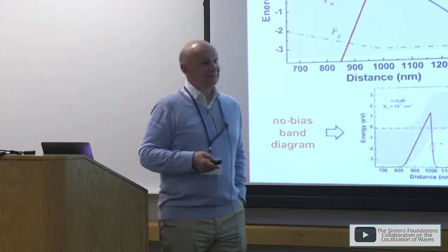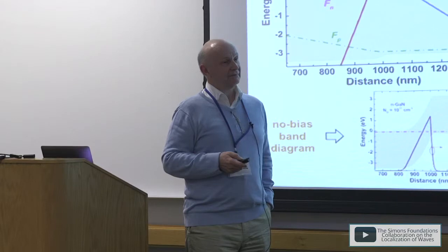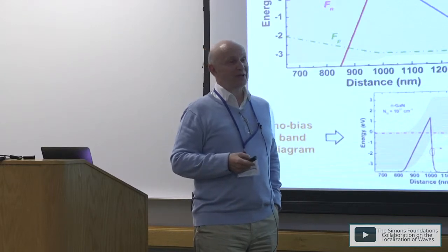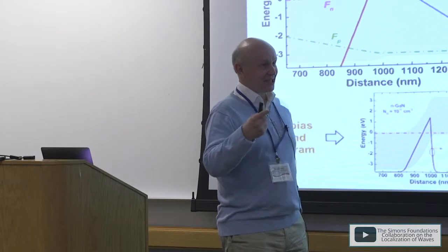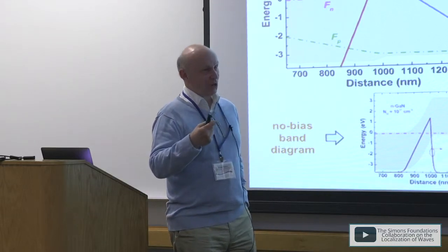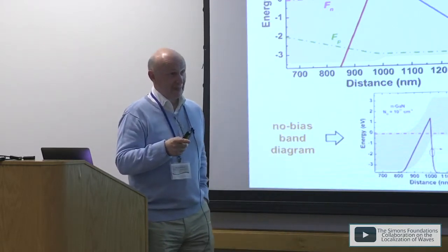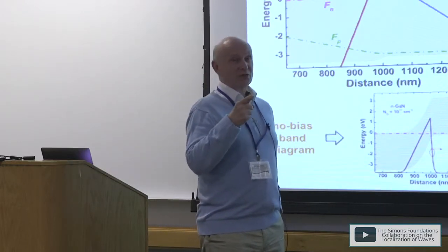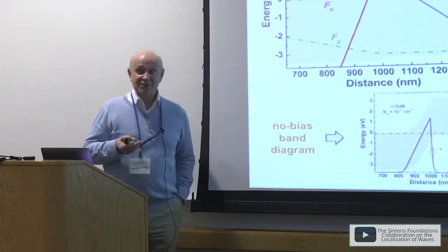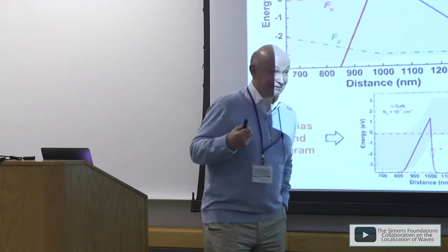I would say that you have some thermally excited electrons and holes in the depletion region, and so you have light, and the energy is supplied by the lattice. Well, it depends if we consider the bulk semiconductors, where the compensation of absorption and light emission takes place, or layered devices. In this case, you can see the luminescence, but the driving force for luminescence is the thermal generation of carriers. So actually, we can get the light from the heat in this particular case.